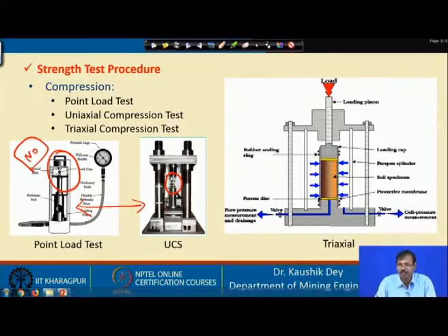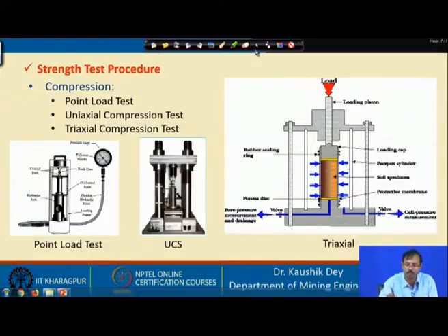Similarly, in triaxial also, specimen preparation is difficult. After that, the experiment procedure is also difficult, where the triaxial load has to be hydraulically provided using some external means. That is why the triaxial cell is essentially required to carry out the triaxial test in the same uniaxial compressive testing machine.